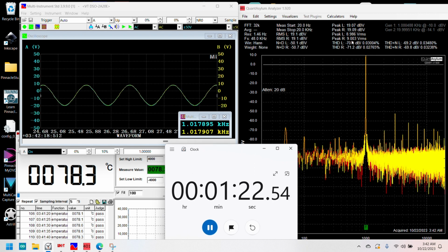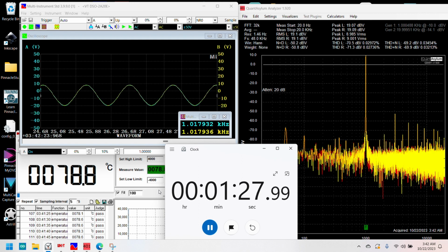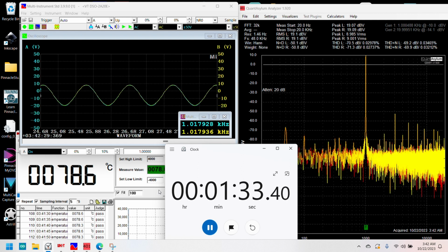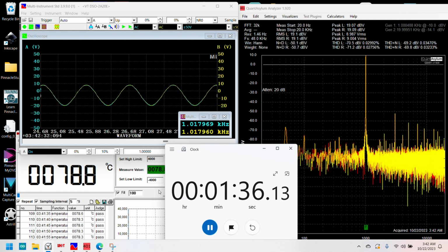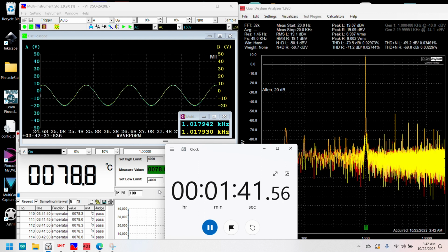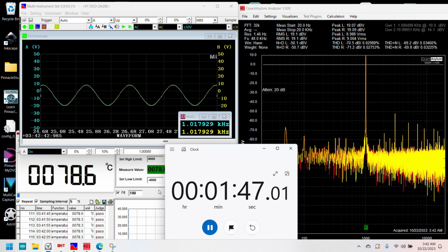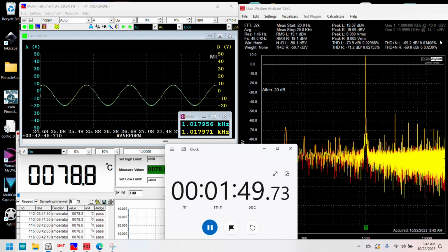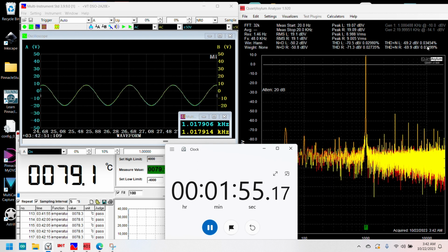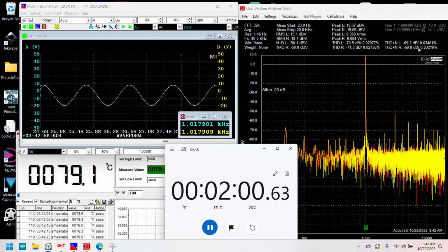So, 8 volt RMS will give you about 20 watt of power at the 4 ohms load. So it means that the left and the right is 40 watts per channel, and that will give you about 80 watts being consumed at the main power supply right now. That's what I'm saying. And at that power output level, we can see that the distortion is pretty good. It's 0.034 for the left and similarly for the right channel.